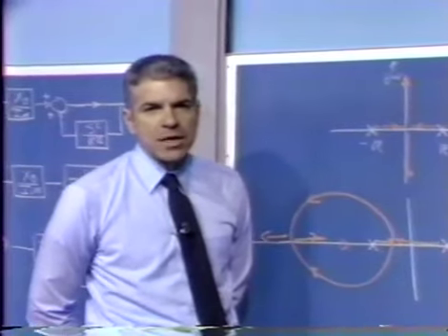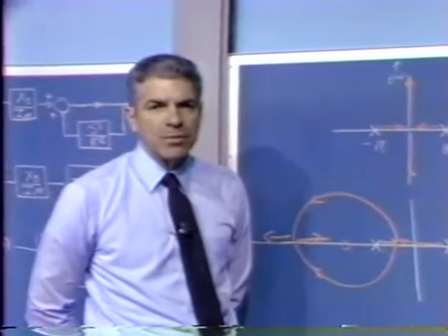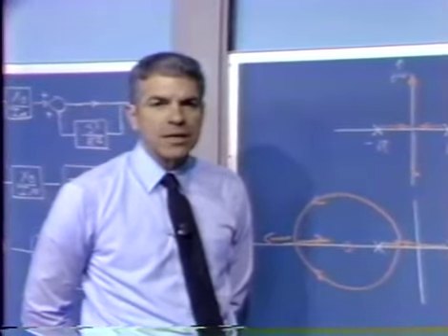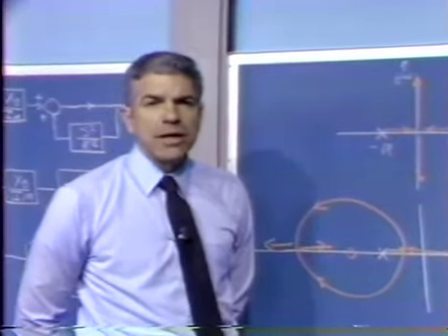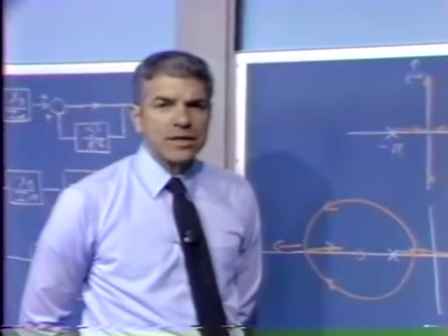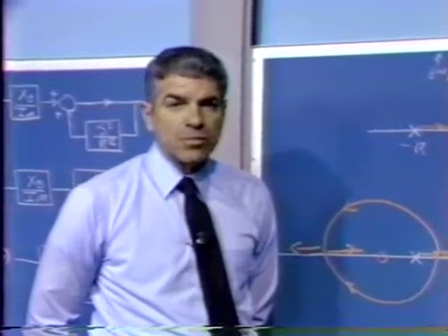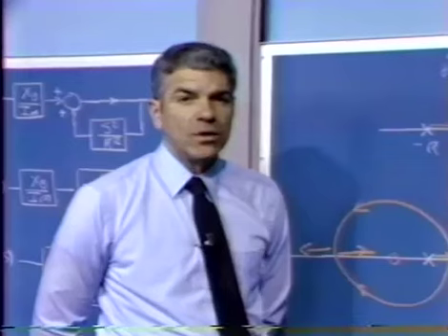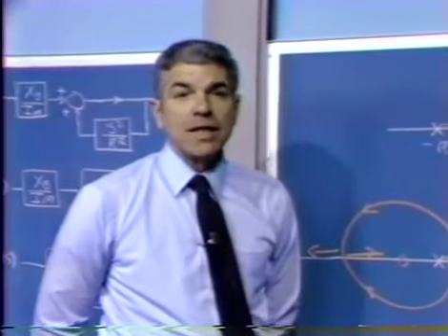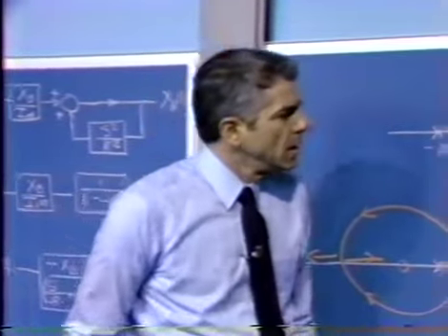There may be additional time constants associated with the magnet. It's a fairly large magnet. There's several thousand turns. We may not be able to very rapidly change the current in the magnet, and so there's probably a time constant associated with the magnet. If we use a lead network rather than simply a zero, we realize that adding a zero to the loop transmission implies somewhere we have to have an amplifier that has unlimited high frequency gain. That's probably not realistic. We probably have to have a pole associated with that zero, the normal lead network kind of transfer function. That would give us an additional pole. So there's certainly other poles in the loop transmission.